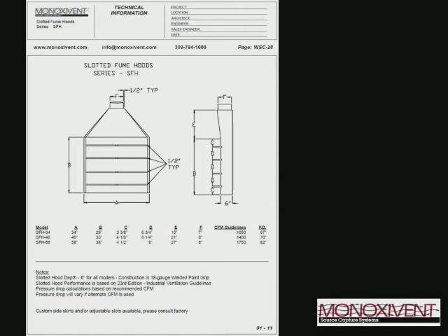So if the situation allows, side skirts are a nice way to prevent turbulent air moving back and forth and changing the path of the exhaust. If the situation allows, that's a nice way to protect it. The more protected the exhaust is, the easier it is to capture.